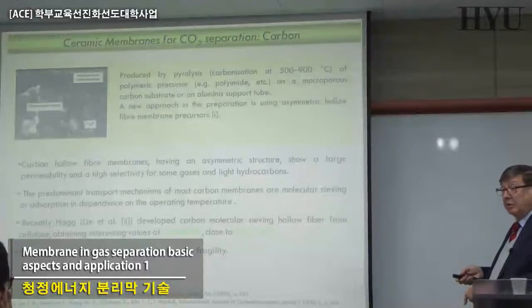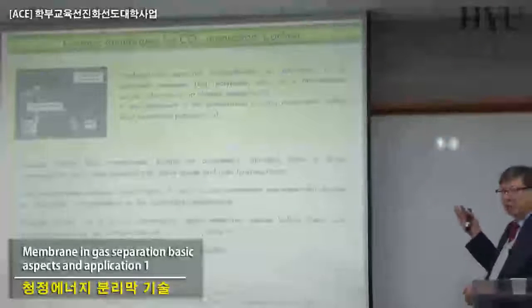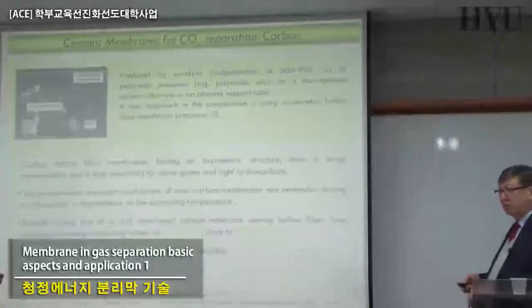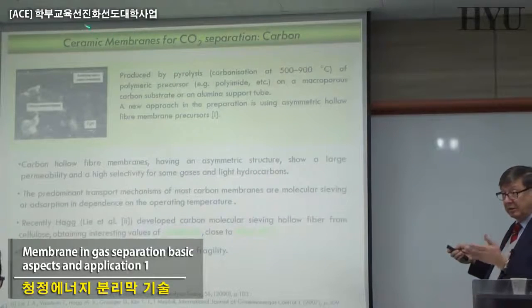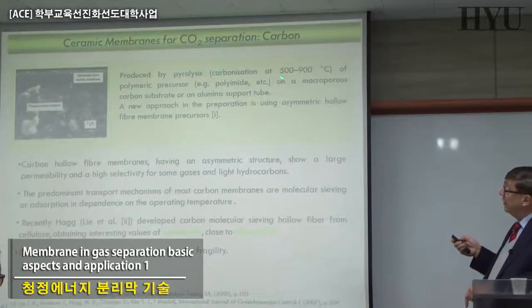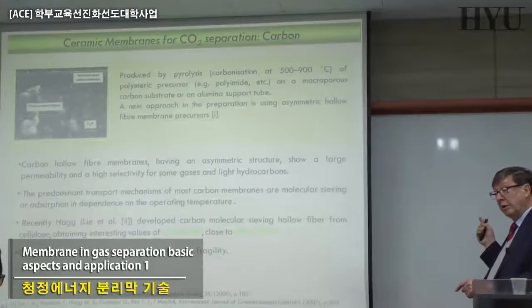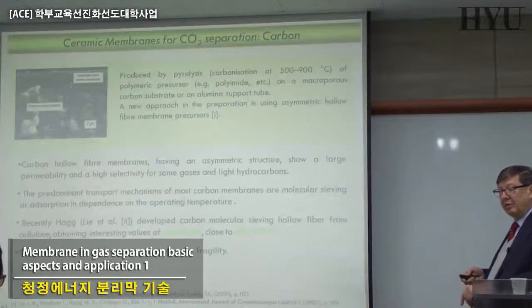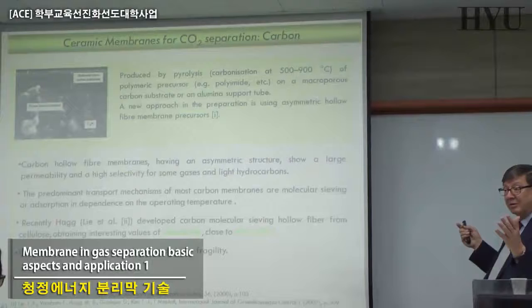Carbon membrane, basically, you can have some polymeric material. Today, people are also preparing hollow fibers from cellulosic material, traditional cellulosic material or others, by pyrolysis. You just burn this material, and at the end you have a decarbonization at very high temperature, between 500 and 900 degrees centigrade. The polymeric precursor can also be polyimide, the one that we can also use as a dense film. You transform all this polymer into carbon. All the rest is gone.